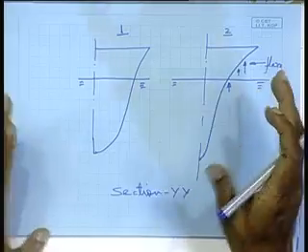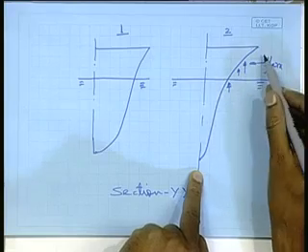In any case, both will be subjected to that load due to the slamming on the water surface, that means the local loading, primarily the local loading. So, which will have greater slamming? Greater slamming will be in the one which is having bigger flare.